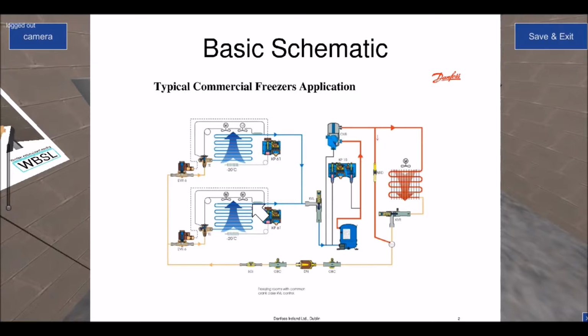The cooler the refrigerant is as it exits, the less pressure pushing down, so the valve will start to modulate in the closed position, therefore reducing the amount of refrigerant that goes into the actual evaporator, therefore causing the liquid to boil off sooner inside the evaporator, therefore giving a larger area over to the superheat zone, therefore increasing the sensible temperature of the refrigerant as it leaves the evaporator, thereby increasing the pressure in the bulb down on the diaphragm, thereby forcing the valve open, allowing more liquid in.